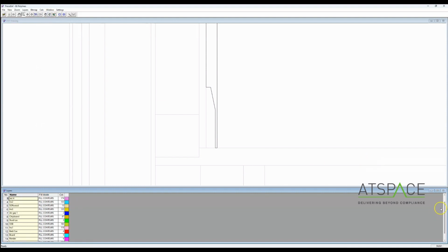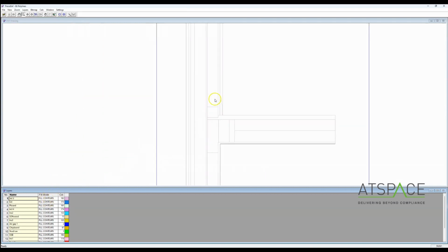It's useful if you're doing steel frame buildings where there's quite intricate bits of steel work within the model, and you want to have that within a layer of insulation. Sometimes rather than drawing that intricate bit of metal and then drawing the insulation intricately around it, it's easier just to draw a block of insulation, draw the metal within it, and then prioritize the steel over the insulation.